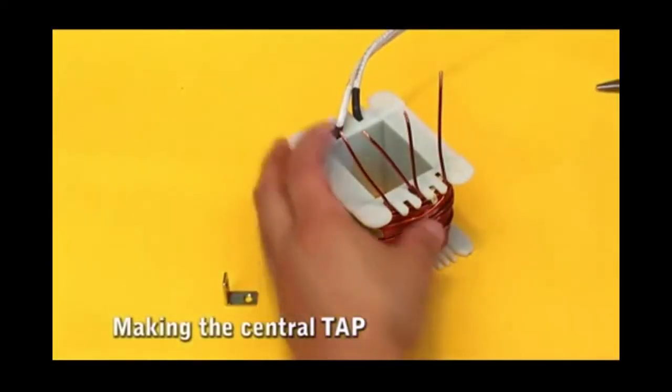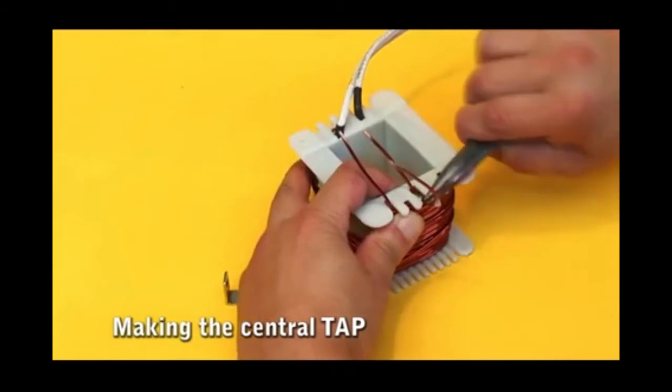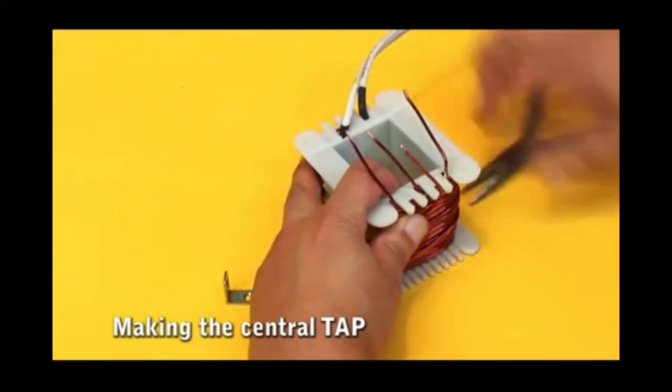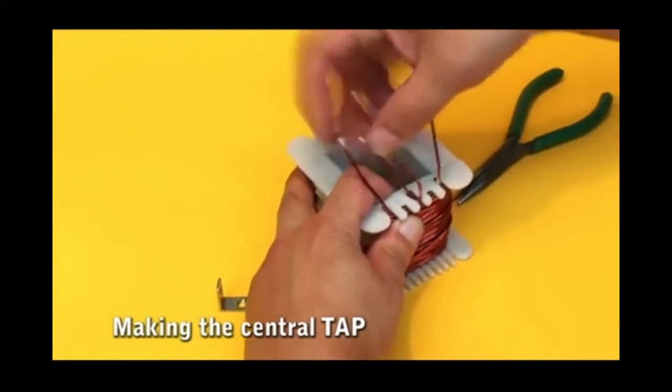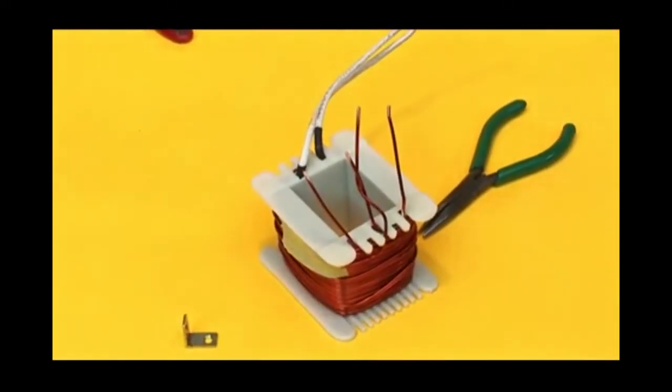It is necessary to join the leading end of one winding with the tail of the other winding. The starting point of one secondary winding must be joined together with the end of the other secondary winding, thus forming the center tap. In order to weld the center tap point, remember to sand the pieces of wire so that there is adhesion of the solder and good conduction.